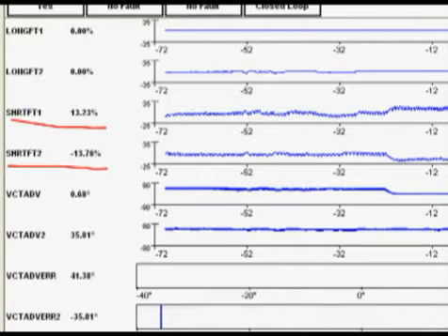But if you go back over toward the left side, when the engine was running at 2,500 RPM, we see that the fuel trims were not nearly as broken. They also were not opposing each other. Like I said, this is a typical appearance of a volumetric efficiency problem, but volumetric efficiency problems generally happen as you increase the RPM. So it could be a restricted precat, that would cause a problem like this, but not under these conditions, because the problem isn't there at 2,500, but it comes there at idle. So there's something causing a change in volumetric efficiency at idle as opposed to 2,500 RPM.